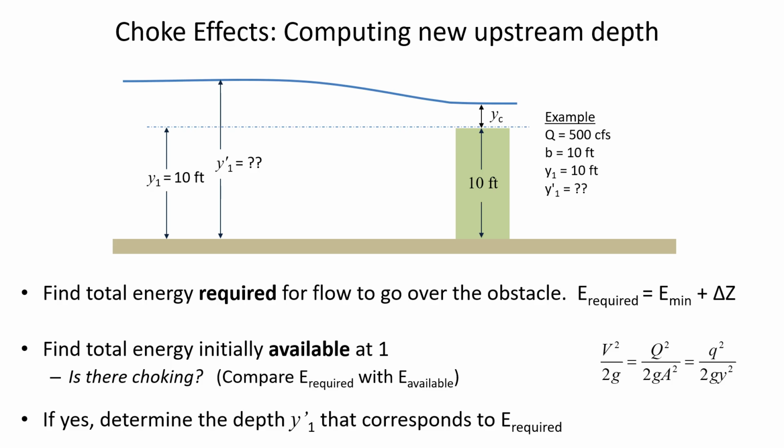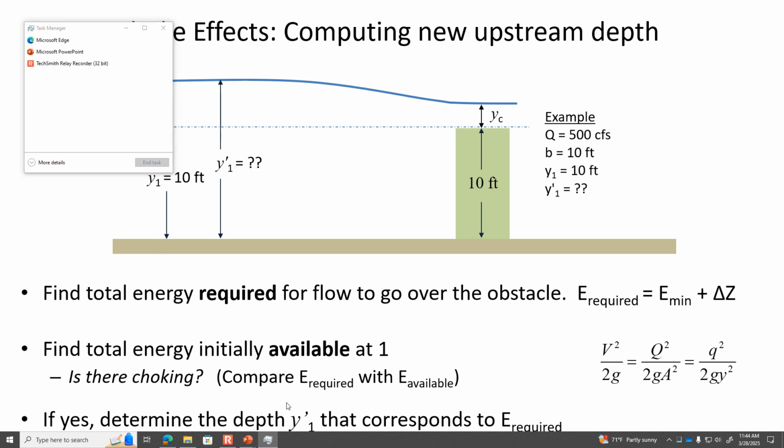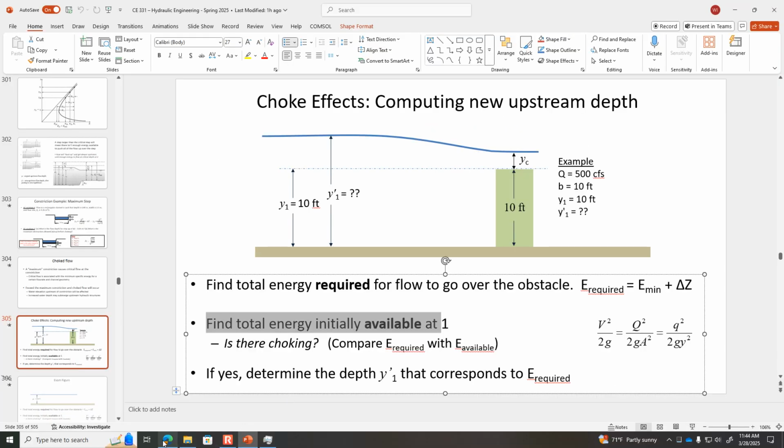16.398 feet. So the water upstream is just barely going to accumulate enough energy to achieve the minimum amount to get over the obstruction. And what we already found was the minimum amount of energy to overcome the obstruction is about 16.4 feet.